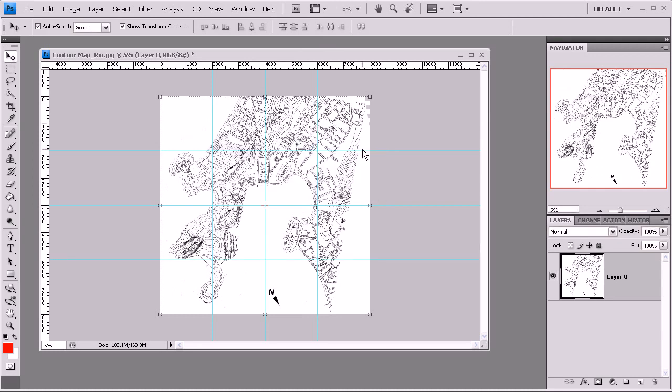Right, so what this is showing us right now is how our site mesh is going to be split up. The reason why we're splitting it up is for two reasons. First of all, it allows our texture sizes to be much smaller if you don't have 32 or 64 gigs of RAM to run the model. And second of all, it allows our site mesh in each case to be slightly smaller. It means that you can have more polys and smaller objects to work with. It's just a way that I like to optimize things to keep each object in the scene relatively small.